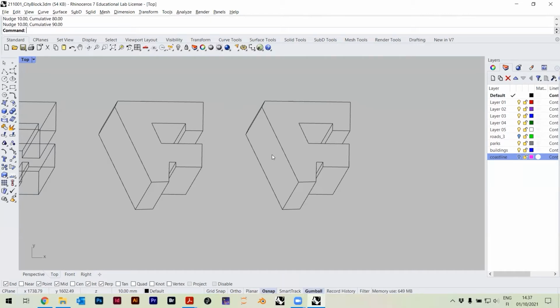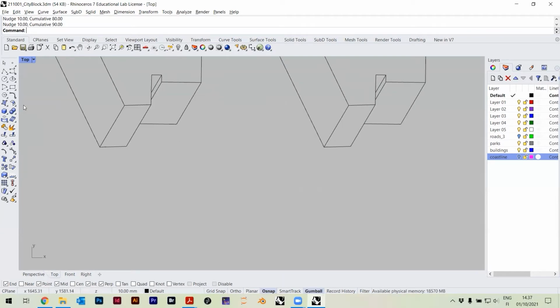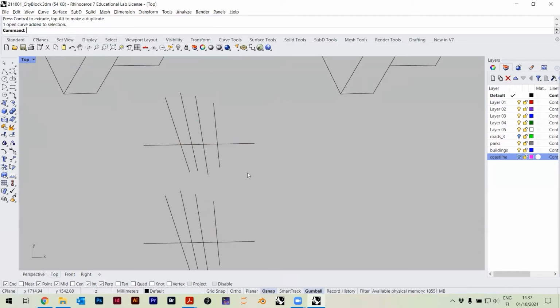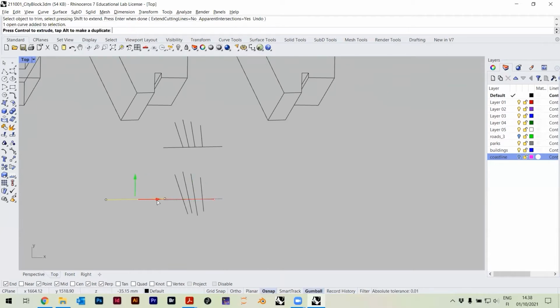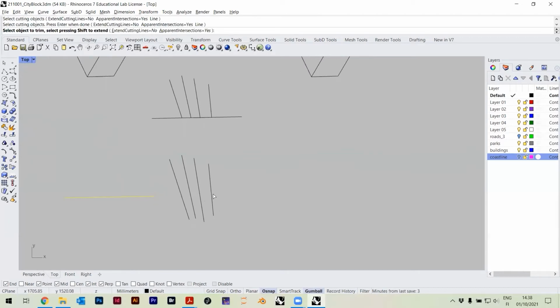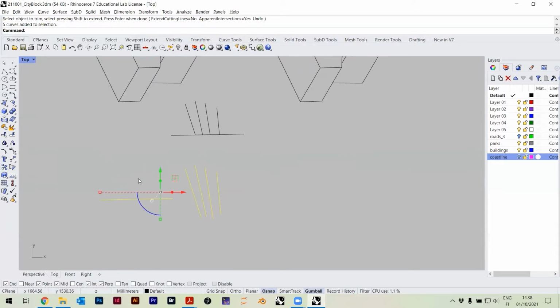But basically, if you have two lines and they intersect, you can always trim. Very easily, if I have lines and this happens, then this I can always trim. I can always take this line here, say trim, select the cutting line, and do this. I think maybe your question was, is it possible to do this? I'm not sure. You see, trim, you can say this is a trimming line, and now I want to trim these ones. Yeah, this doesn't really work. So they have to actually intersect. But I can do the opposite.